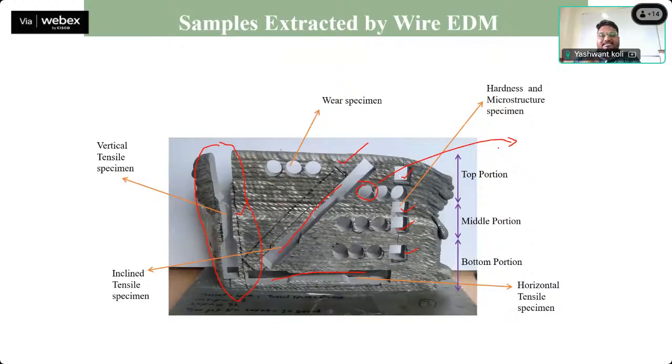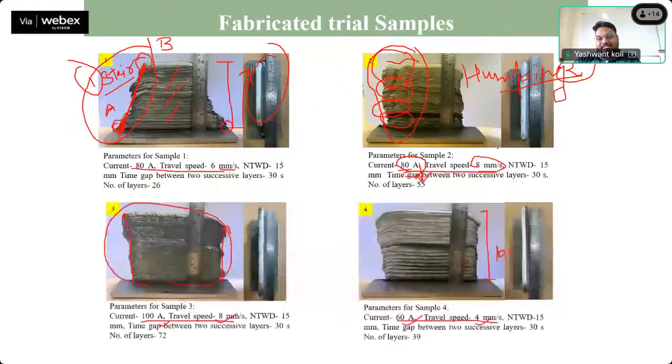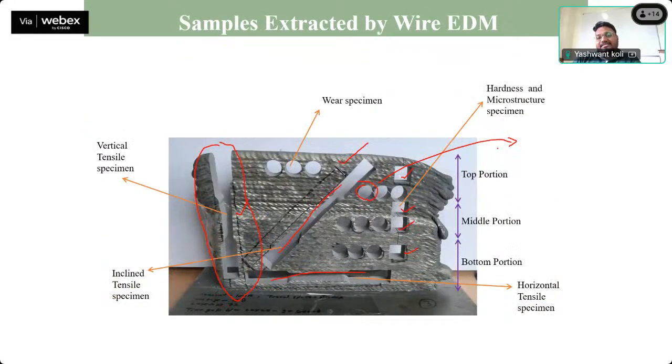If it forms some residual stresses, it can be helpful or it can be detrimental to the component, so we have to take that into consideration. We can compare both samples, the as-fabricated sample, the polished results, and by grinding or by CNC milling, how the values are changing. So that can be done.